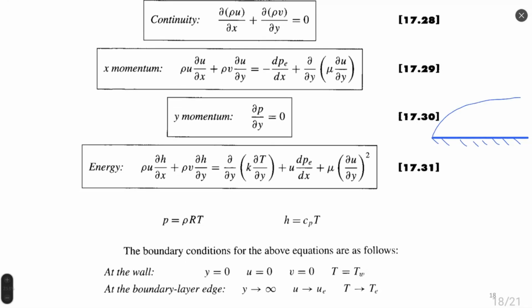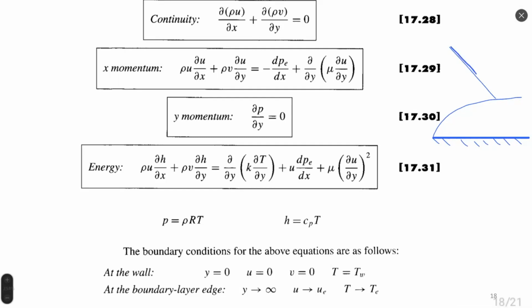This is boundary layer, and for example, we have supersonic flow, or flow with shock wave. Okay, let's see here. Shock wave is represented by pressure gradient, right? So pressure lines, or constant pressure lines, are very close here inside.